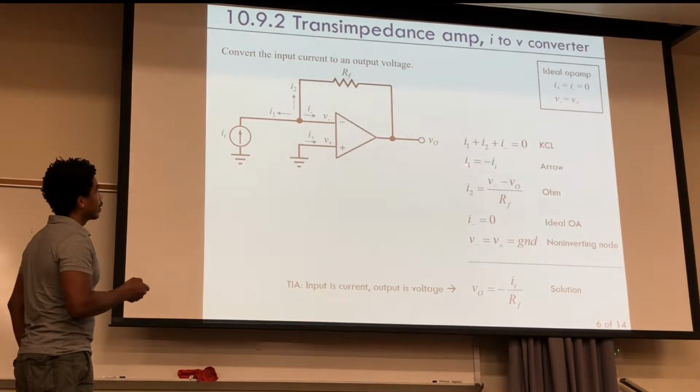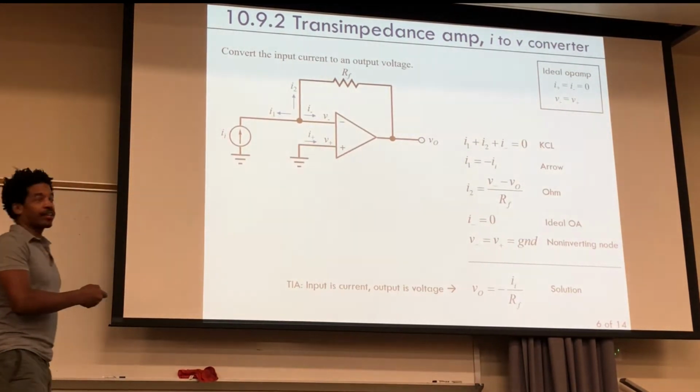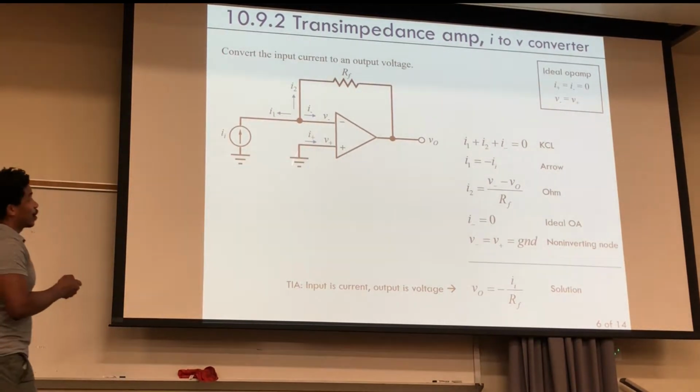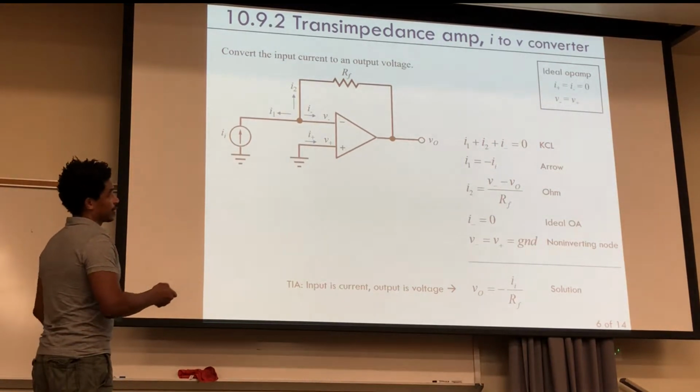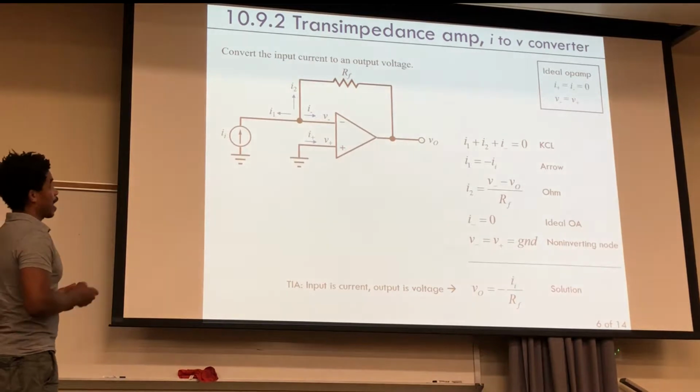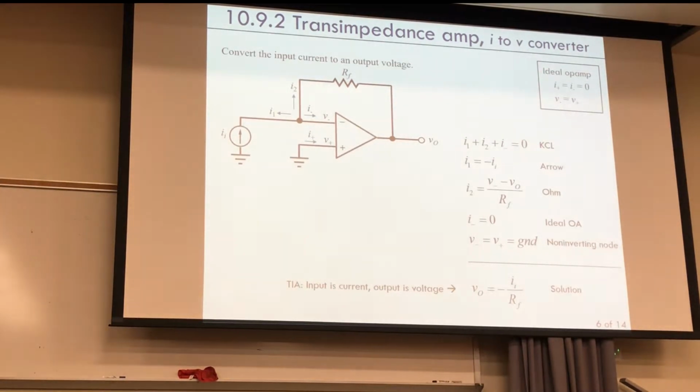So I1, right here, well, that's the negative of Ii. The current's coming in here like that. Here's the direction of I1. It's the same magnitude, but it's pointing the opposite direction. I could have these arrows go into the node. That's fine. If they go into the node, it's just that all these are negative. It's the same equation. I can even have some going in and some going out. I just have to define in my equation, well, are the ones going in negative, or are they positive? Are the ones going out positive or negative?